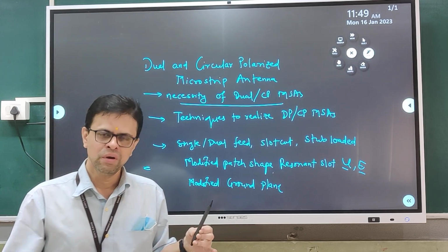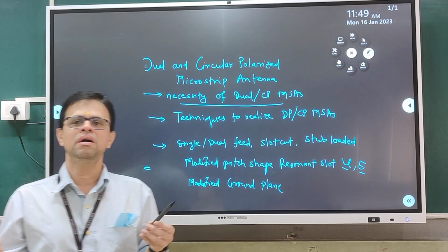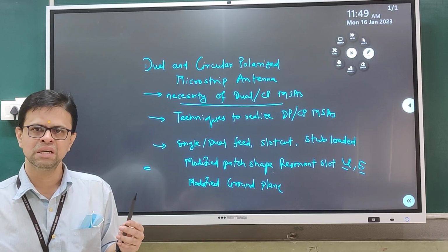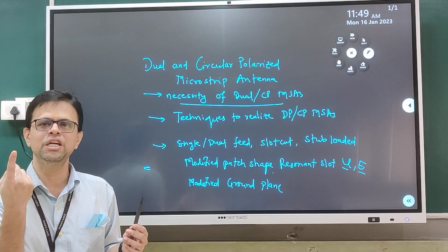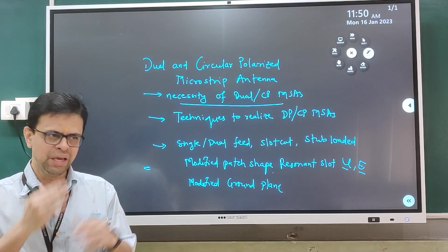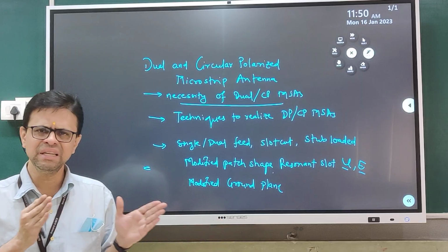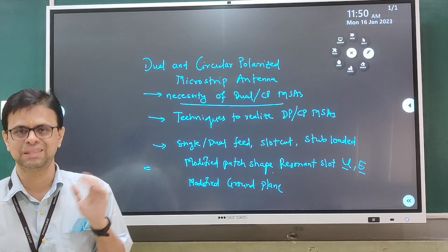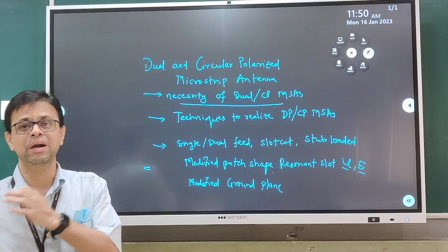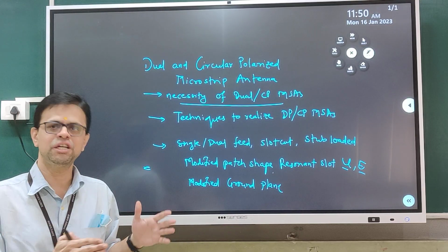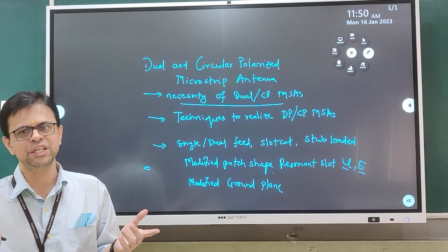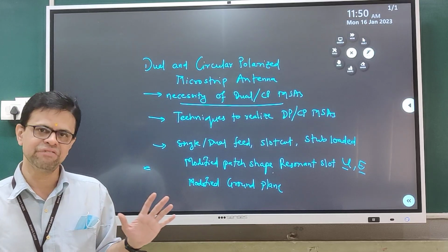Now as we know, especially in all our GSM, Wi-Fi band applications or anything above 500 MHz, there is a line of sight communication which takes place between the transmitter and the receiver. In that process, the signal undergoes multiple paths. Due to those multiple paths, reflections also come across, and whenever there is a reflection from any object, there is bound to be a change of direction of the re-radiated electric field.